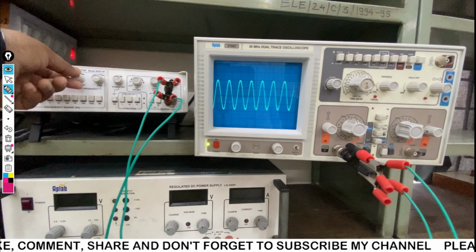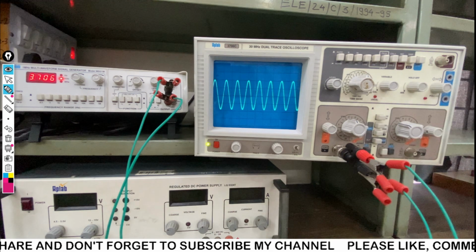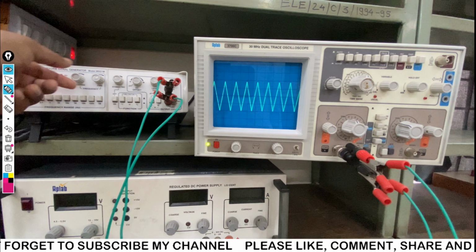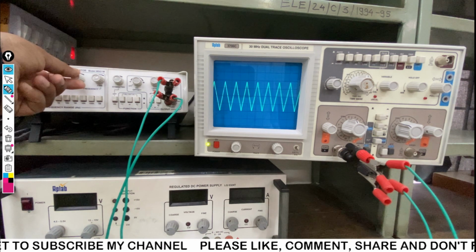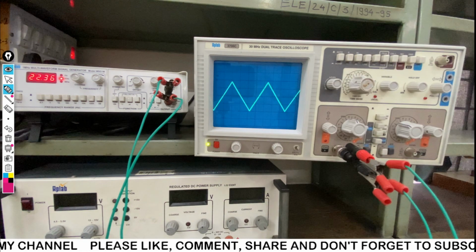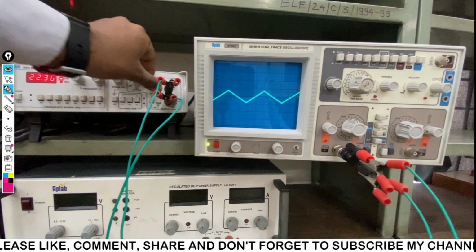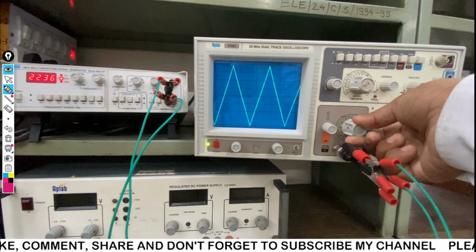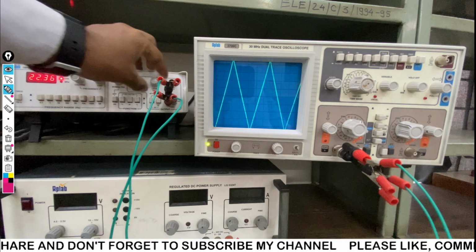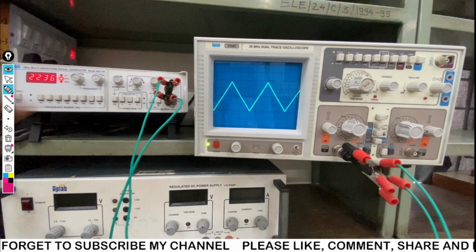We are not going to use this waveform for the calculation. We have to make at least two crests or two troughs. This is the horizontal direction button. You can see here, this is a triangular waveform where we can have variation in frequency as well as variation in the amplitude. So we have to adjust at each point. When the frequency is more, we have to adjust the time per division knob. When the frequency is less, we have to adjust the time per division knob. When the amplitude is more, we have to adjust the voltage per division knob. If the amplitude is less, we have to adjust the voltage per division knob. So these are the basic things that we require.